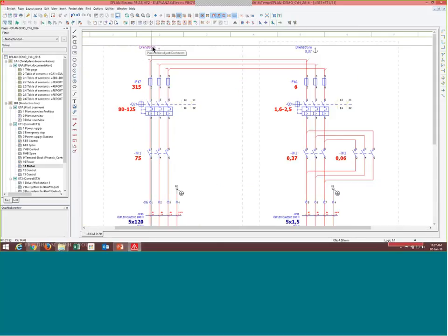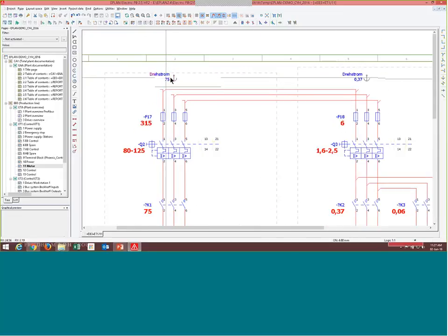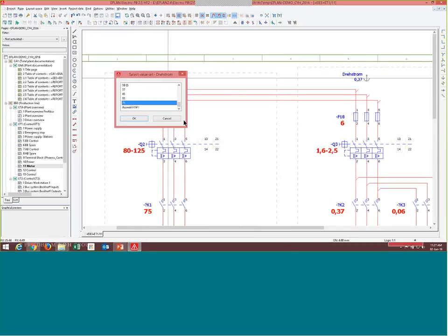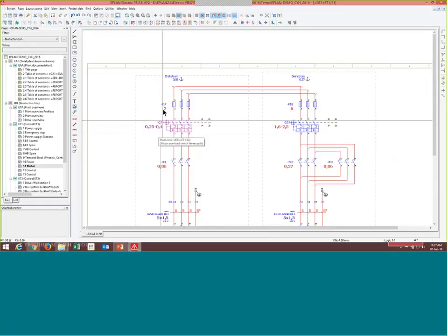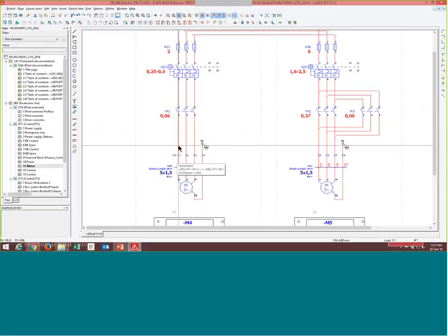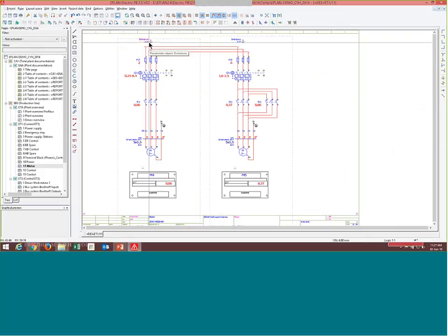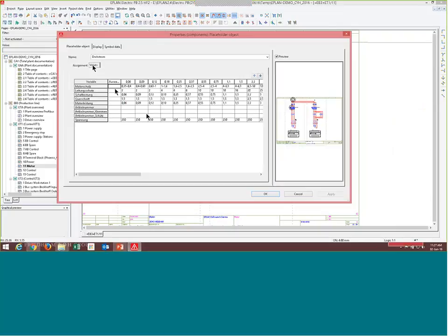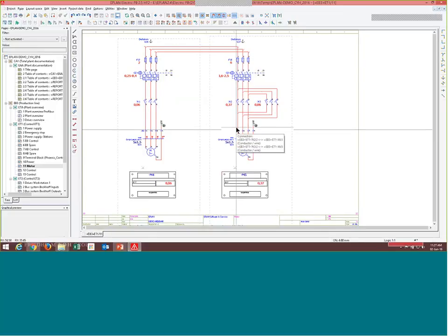Okay, and then we have a placeholder object function. So let's say you would like to change the motor rating from 75 to a different rating. So you can just right click, assign value set. So let's say you change to the smallest one, 006. Okay, and as you can see here, the fuse rating, the motor breakers, and the cable size will change automatically according to the motor's kilowatt. Okay. So this can all be customized and set according to your company standard by using these tables. Right. So you can always customize and put in any information that you want. Okay. So this is how easily we can just use the macro to insert the drawing.